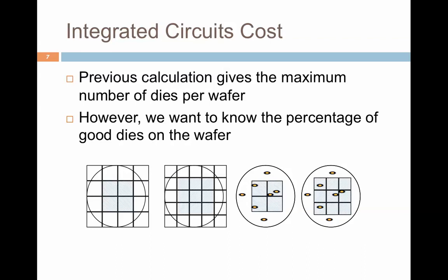So at the most bottom layers, you would see most of the logic. Layers 1, 2, 3, probably up to 4. These are all the layers for your logic, right? So logic and mostly your caches. So this is your processor architecture, and so on. So you have 3-4 metal layers just for designing that, okay?